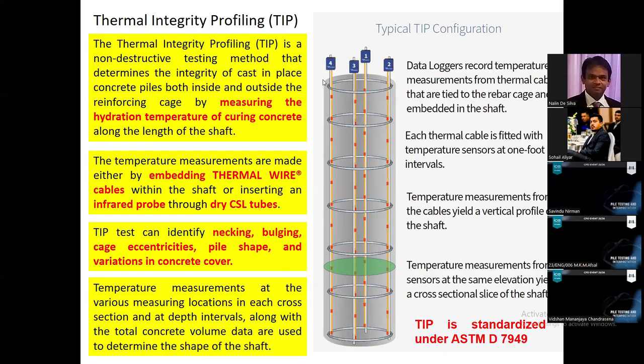So you know that during concrete curing, the heat of hydration is happening. This heat of hydration increases the temperature of the pile. This increase in the temperature of the pile can be detected by these thermal sensors, and that temperature reading can be used to interpret the integrity of the pile. So that is the basic concept.